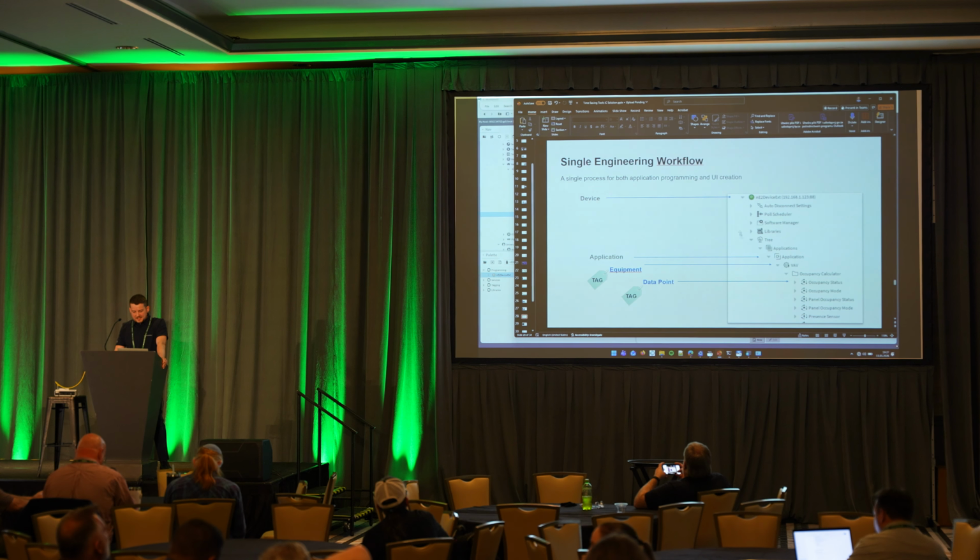So this is the tree inside the device for our VAV controller. There are hundreds of BACnet points inside our VAV controller, but only the ones that we want you to have on the web UI are tagged and being exposed for convenience of local operation just through the web.